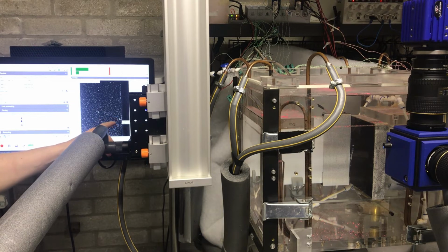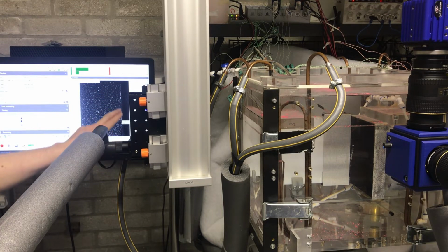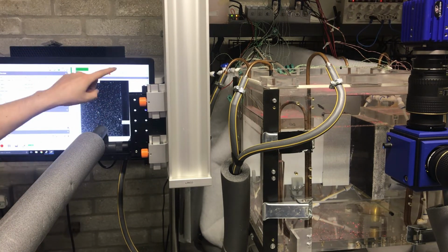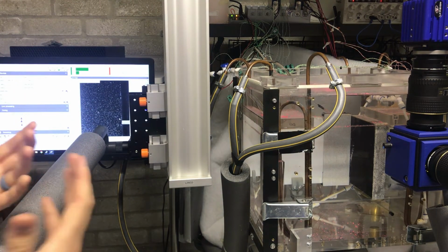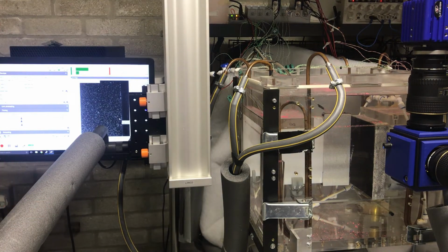But even if we could correct that, we would find that it's quite difficult to get seeding particles very, very close to a surface. And actually the way I approach that in this experiment is to seed from below very near to the surface by observing where the near wall fluid was being drawn from. Now that strategy won't work everywhere, but it did work here.